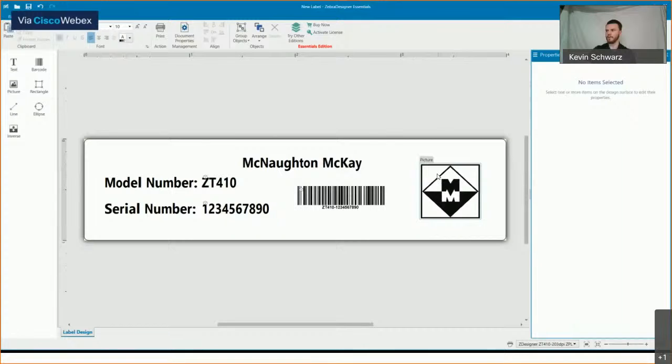Now, for the picture format types, it'll allow either a JPEG or a PNG image, depending on which one your current format is in. That's what's accepted in the Zebra Designer, and that's what the printer will accept. You can store images into the printer, instead of having them in your template file, and then just have the template file recall that image if you wanted to. But for this demo, we're not going to do that.